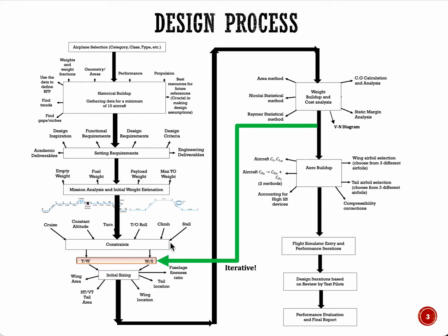So essentially, you're going to have to go back and calculate the new surface area and new thrust required based on the result from the weight estimation, and then put it all through the component weight estimation again, and do the iteration until you get a converged solution. When I say converged, the input to this process should be relatively the same as the output from the weight estimation. As long as you can ensure that, then you should be good, right?